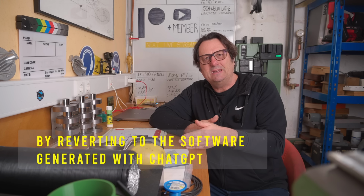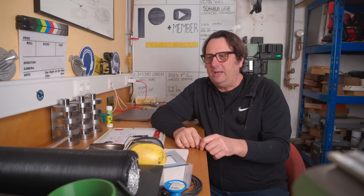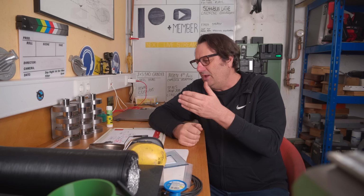As long as I can command a spindle speed, have it set it and hold it stably, I'm actually already better off than I was before. Because before, if I wanted 2000 RPM, I'd have to estimate roughly what gear ratio I had and then give it some fake number like 80 to give the correct output because the scaling was never right for any specific speed. If I can command a speed and it'll hold a speed, that's already an improvement.